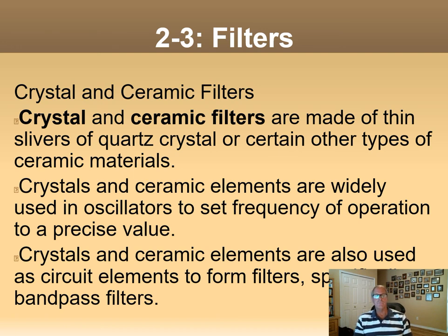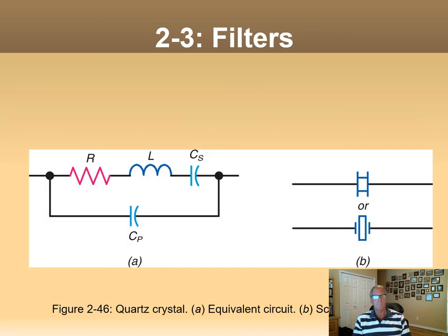Crystal and ceramic filters. Crystals basically are filters. You've heard of crystals, those are frequency selective devices. Not too many ceramic filters these days. Don't see many of those around because crystals have become less expensive. This is what a crystal looks like in real life. I mean, a model. This is a model of a crystal. We have an R, L, series C, and a parallel C. So it's a tuned circuit. But if you were to try to make a tuned circuit out of discrete inductors, capacitors, and resistors, you could never get the Q that you achieve out of a real crystal.